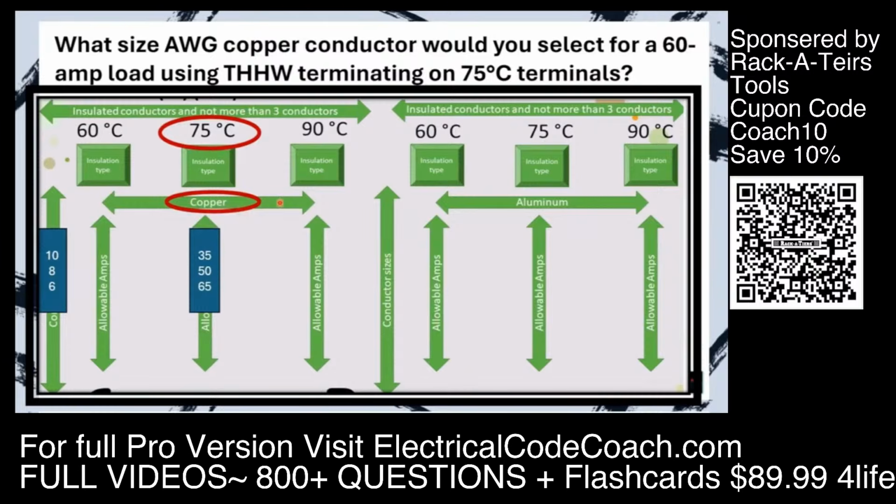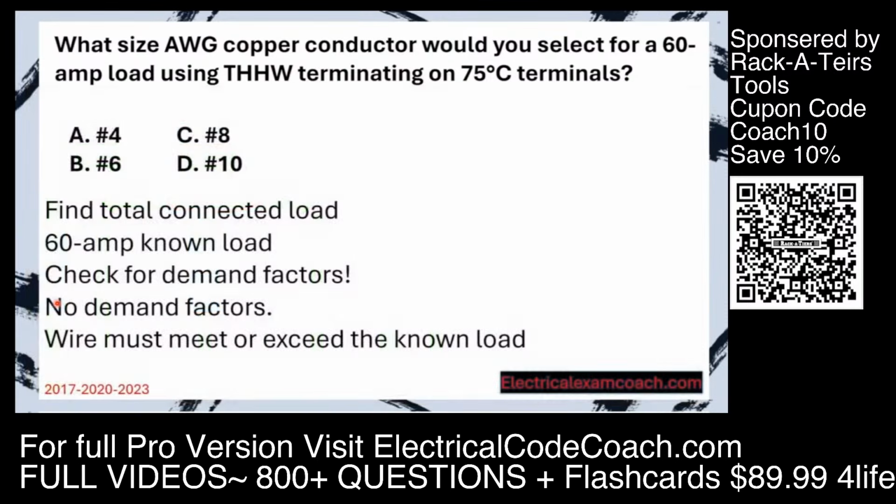What type of metal? Copper. What are my terminal ratings? They are 75 degrees C. What is my known load? 60. I'm going to start down the 75 degrees C column until I find a wire that covers the known load, and then I'm going to use a straight edge to come over and select my size wire. And in this case, you would put it on a 6-gauge wire. We go back and we select B. Great job.